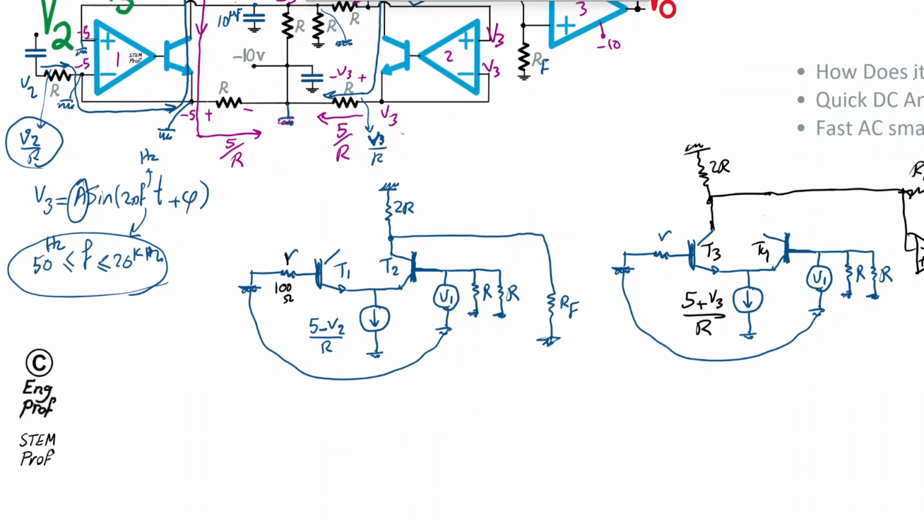And let's take a look at V1. V1 appears across 2 base emitters. So as a result, I base AC, I base 2, is passing through this circuit. So I can say I base 2 is equal to the total voltage V1 divided by RB, or R base of this transistor, and RB, R base of this transistor.